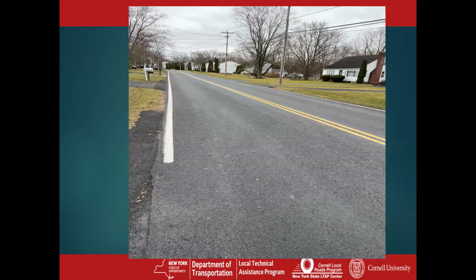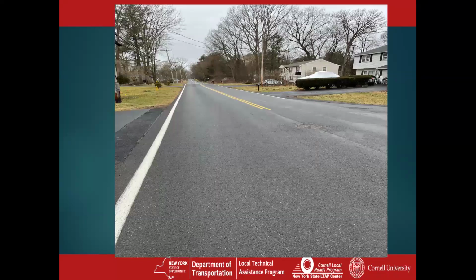And here's a perfect example of a pavement that would be triggering your interest in doing a surface treatment, because you're looking at that pock-marked surface. There's a lot of moisture in the air, so there's still a lot of moisture on that pavement surface. You're getting that pock-marked look, which means water is being absorbed into the surface, but your pavement's in great shape. Again, you're just looking at it from a different angle. That pavement is in great shape.